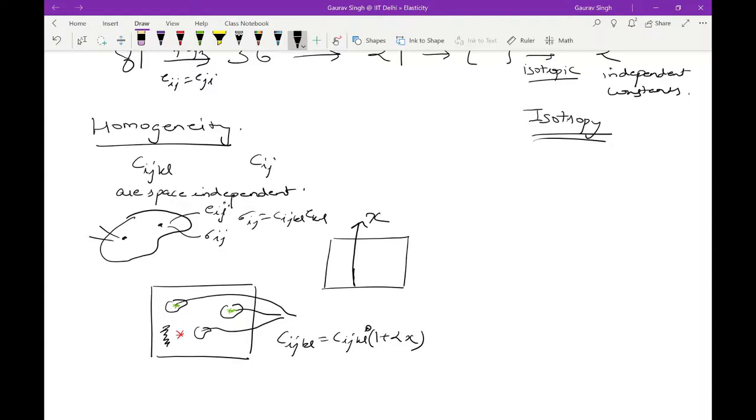So this is a functionally graded material, clearly non-homogeneous, and many a times in aerospace or automotive industries, these materials are artificially made so that you can define how the elastic properties vary with space. Okay, so you can also have this. I'm only taking one dimension, but I hope you can see that x, y, and even z can come. Okay, so if the elastic properties vary exponentially, this is how it looks like.